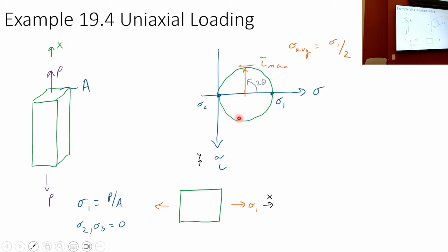These transformations allow us to go between maximum principal stresses, at least in a plane, and maximum shear stresses, at least in a plane. So it allows us to figure out if the ductile material has normal loading, what is the equivalent shear stress that we have to be worried about for that ductile material.